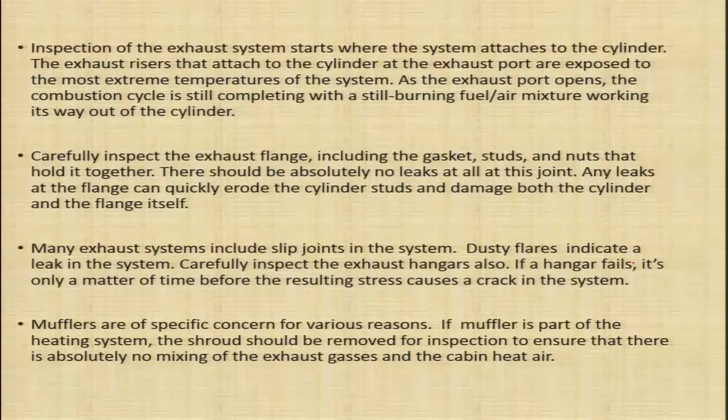Carefully inspect the exhaust flange including the gasket, studs and nuts that hold it together. So, this area is to be inspected very thoroughly. We need to inspect the exhaust flange, the gasket, and the studs and nuts that hold the exhaust tubes, the exhaust stacks, to the exhaust port of the cylinder.